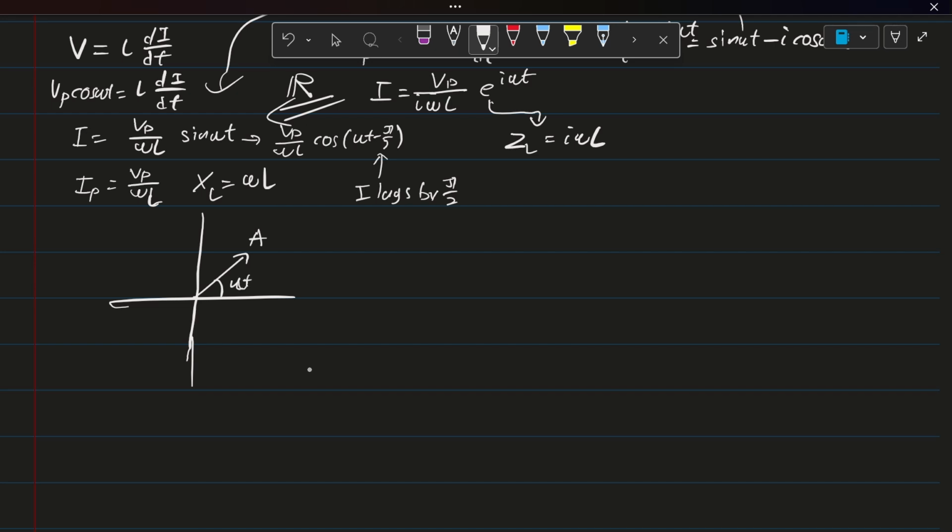And so this might be your first function, and then you might have another function which you call B as the peak, and then there's this difference which you call phi. This is what is drawn within a phasor diagram. So this helps you to visualize which one is leading, which one is lagging, and so on. You could plot it as long as you know the function of your current and your voltage.